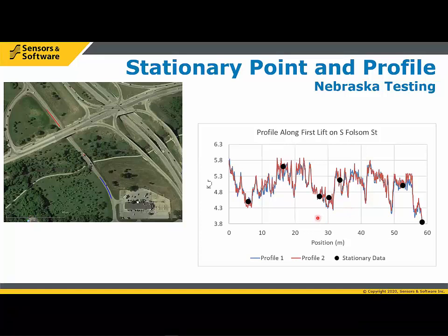And what you want is enough variation in the permittivity to give a good variation in the density. So in other words, if you came along and had a flat profile here with no variation, you'd really only have 1 point. And presumably that's 1 point on that calibration curve. So ideally you want a long enough stretch of line that you can see extremes in the data. So you can see lows and highs, and ideally a number of them, so you can get enough representative values of different permittivities and presumably different densities, so you can actually build that calibration curve. And so it certainly is tens of meters of line are desirable to get enough variation. And we have seen some lines where it's almost perfectly flat, so there isn't significant variation.